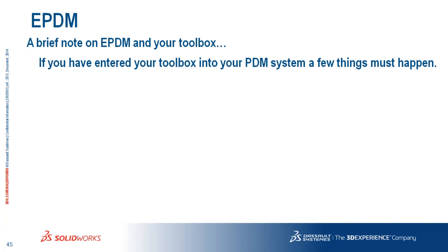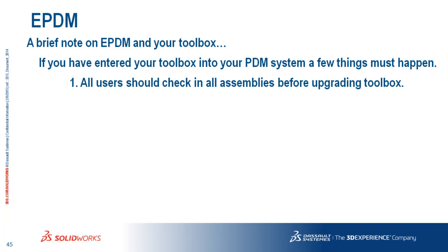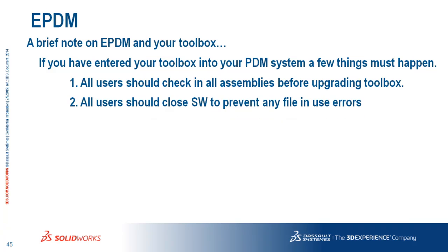EPDM. We're just going to talk briefly about this one. EPDM and your toolbox. If you have entered your toolbox into the PDM system, a few things must happen. One, all users should check in their assemblies before upgrading toolbox. Two, all users should close SOLIDWORKS to prevent any file in use errors. This is the mass deployment issue where write access is denied.